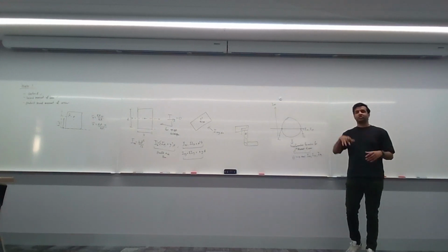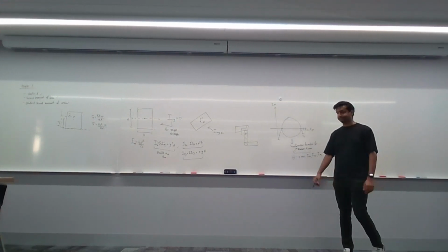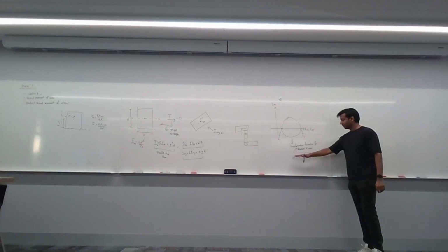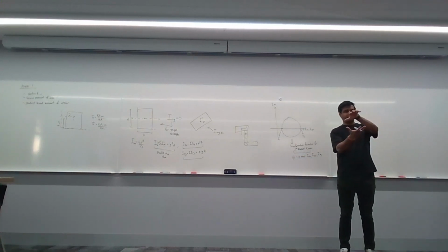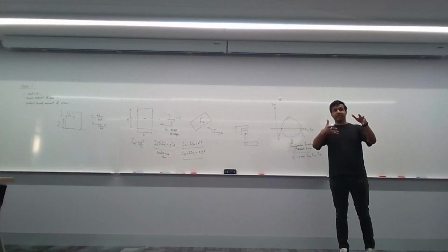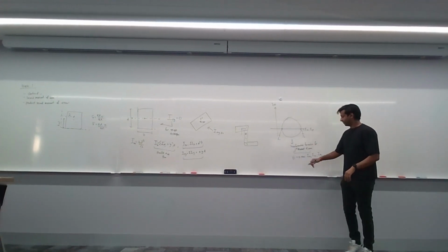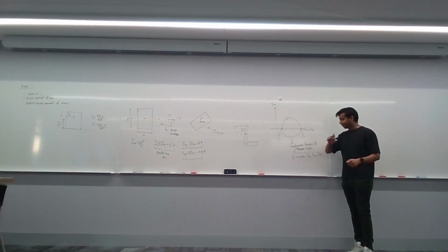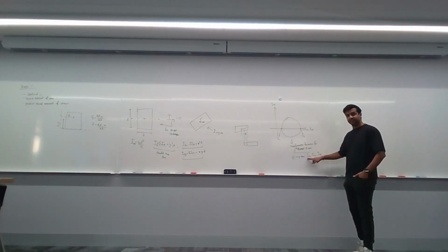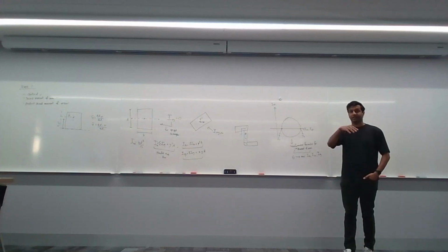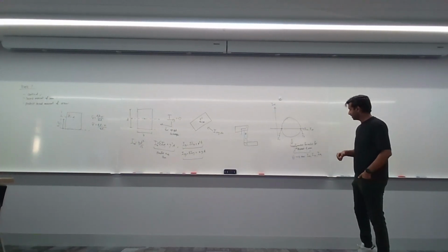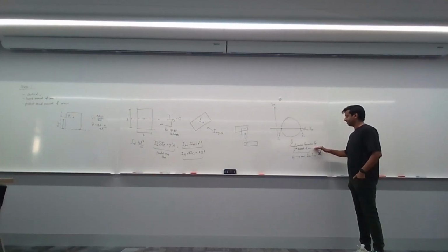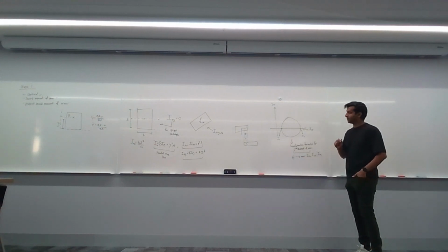They're very similar to the stress transformation formulas from your Mohr circle. Given a particular angle, let's say in real life you're rotating it, say 20 degrees anti-clockwise, for example, that means theta would be 20 degrees. And then from that you can calculate what Ixx, Iyy, and Ixy is, the new values. Okay, so those are your transformation formulas.